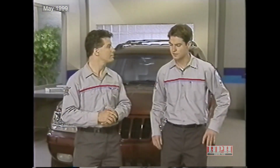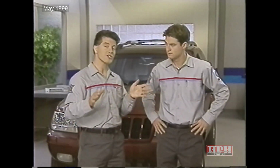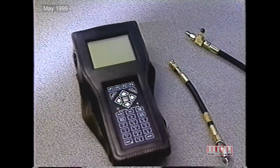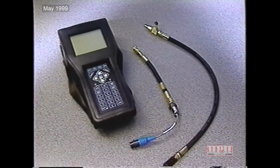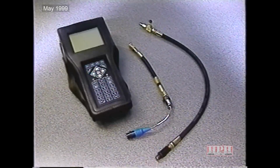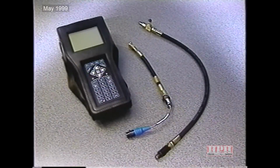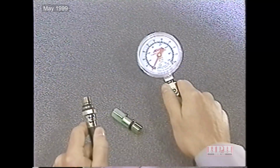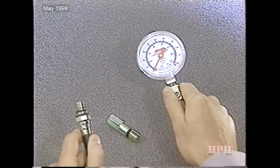Well, what's the best way of isolating the problem inside the engine without tearing it down? By performing a cylinder compression pressure test. To perform the compression test, you'll need a DRB3 and PEP module, adapter number 8116, and a transducer. The transducer plugs into channel 1 of the PEP module, and the adapter attaches to the transducer. If you don't have the DRB3 readily available, this test can also be performed using the compression gauge.